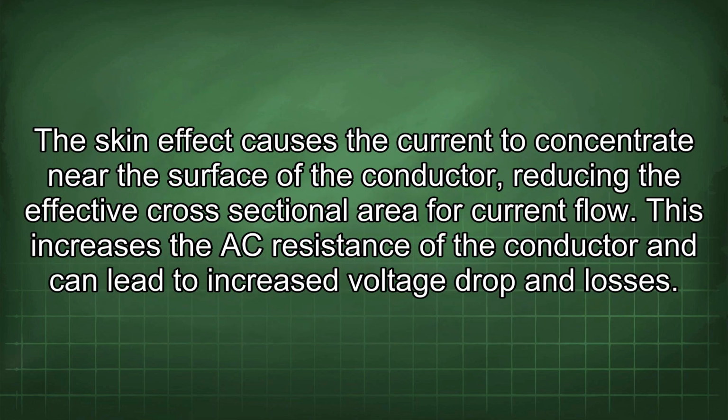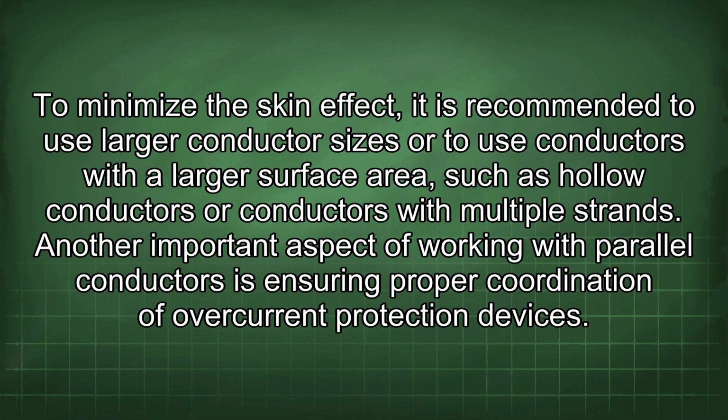The skin effect is another phenomenon that affects the impedance of conductors at higher frequencies. The skin effect causes the current to concentrate near the surface of the conductor, reducing the effective cross-sectional area for current flow. This increases the AC resistance of the conductor and can lead to increased voltage drop and losses. To minimize the skin effect, it is recommended to use larger conductor sizes or to use conductors with a larger surface area, such as hollow conductors or conductors with multiple strands.